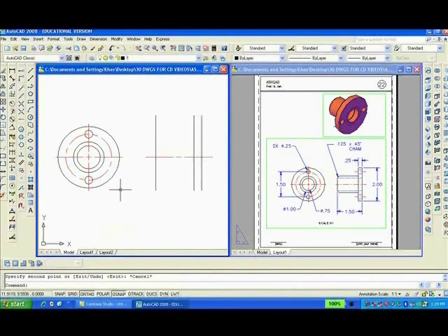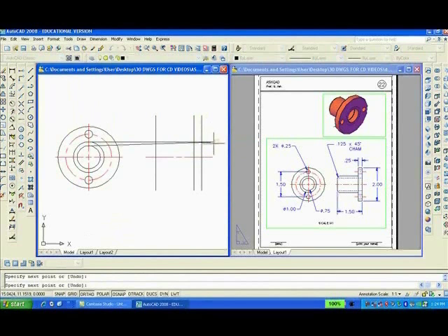In addition, we can make a line from here over and another line from here over. I follow that up, escape, undo, draw another line from this intersection here. And we can trim, TR, enter, trim. We can trim from that line into these two. We can also draw a line from this intersection here like that and use the fillet command, F enter, with radius to 0 to clean up the intersections.